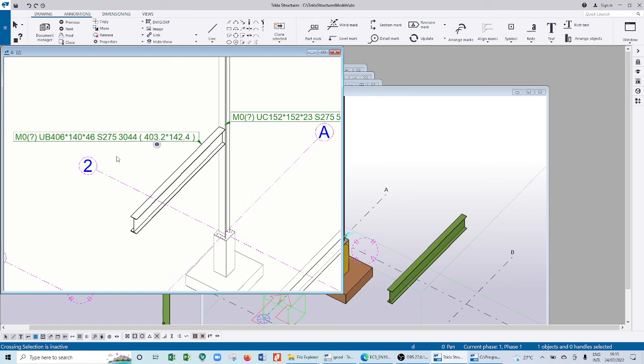Maybe I beg to stop here, but use the same principle, because time is again hard. As long as you model your structure, once you've modeled, make sure that you specify this. So the moment you have set it, then you generate the drawing. Once you have generated the drawing, it will bring the drawing without the part marks. So when you want any part to be detailed, you only right click on that part, then say add the part mark. It will bring what you want. So if I want the size, everything that someone will use at site, I will do that.